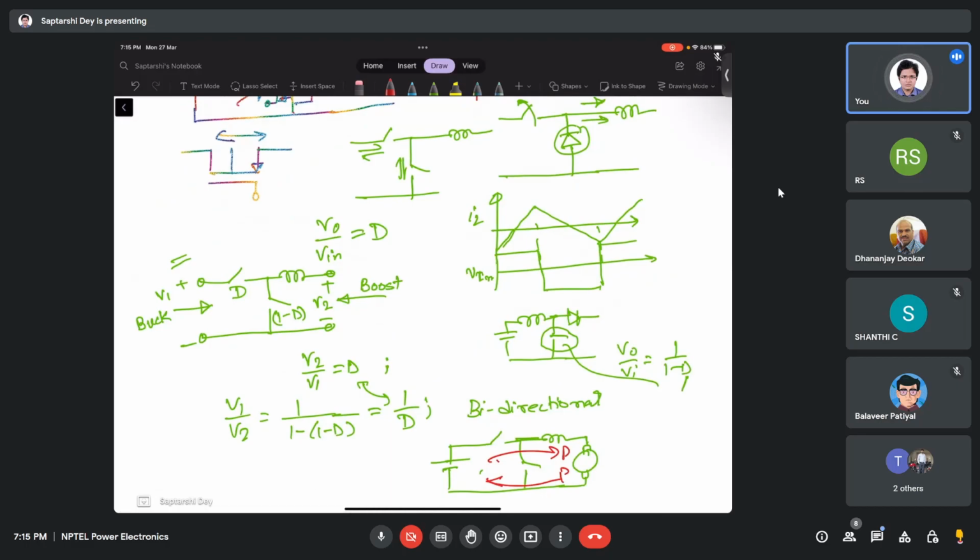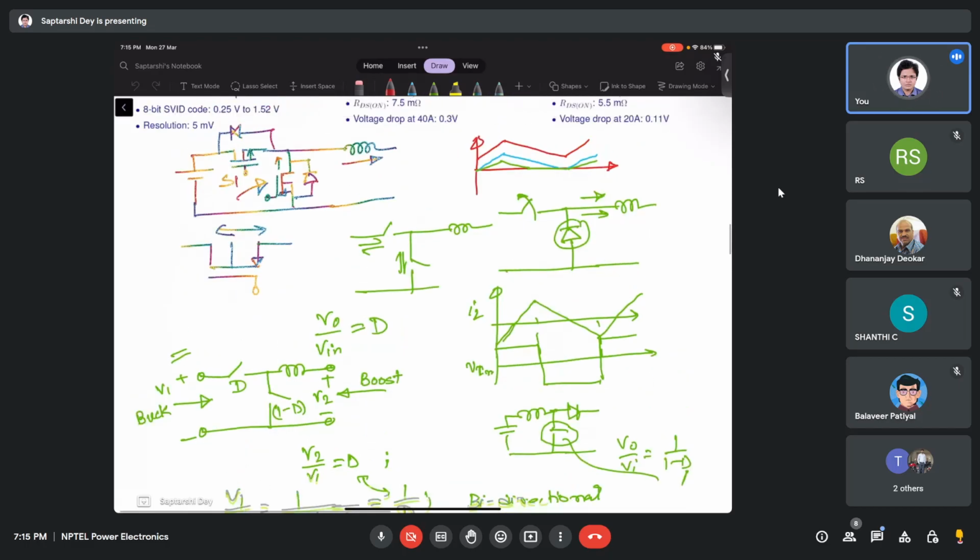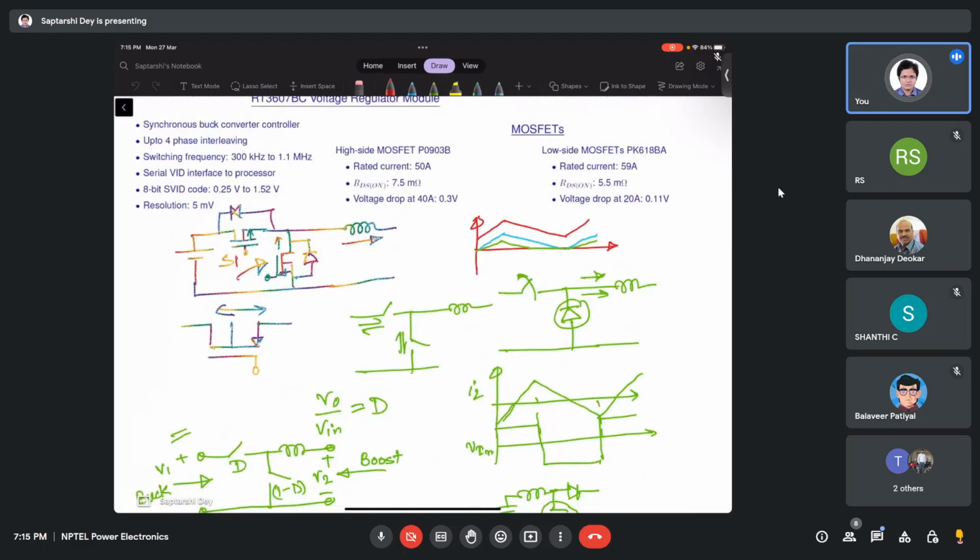The switching loss is much less in this converter because of the diodes. When the primary switch S1 is turned off, this current goes through the diode first, so the voltage drops to 0.7 volt. Then, because the switch takes time to turn on anyway, when the switch is turning on, it sees a very low voltage.